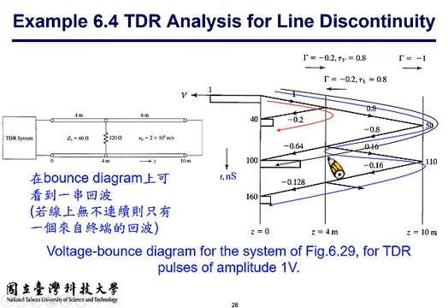One at this interface, which is minus 0.2, and the other is at this interface, the short termination, which is minus 1. So the product of the additional two reflections is what? Positive 0.2, because you have minus 0.2 times minus 1. So you have a 0.2 for each additional term.